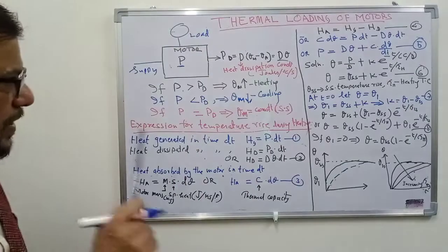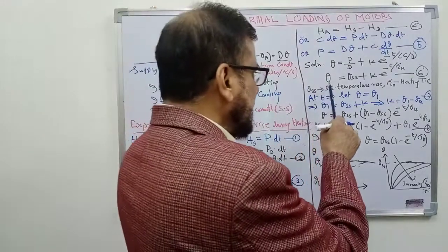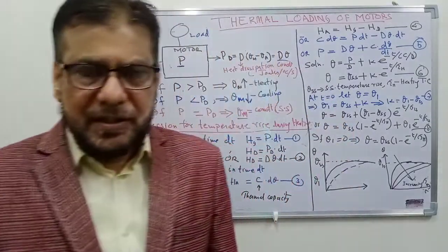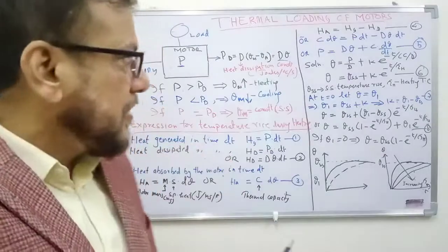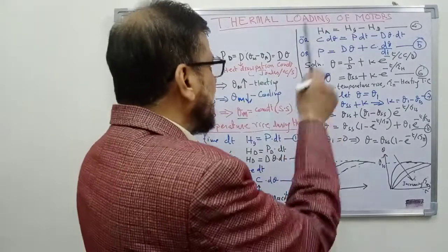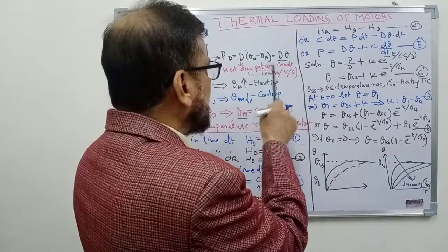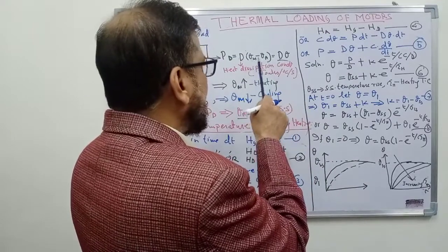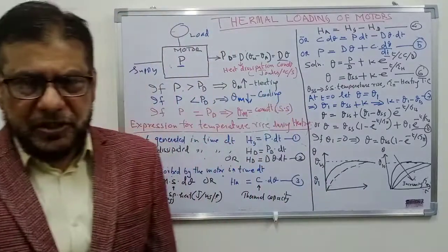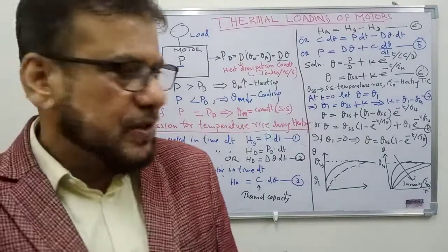You must remember that theta is the temperature rise. It is not the actual temperature of the motor. It is the temperature of the motor above the ambient temperature that you can see from here. Theta is theta m minus theta a. Motor temperature minus the ambient temperature.